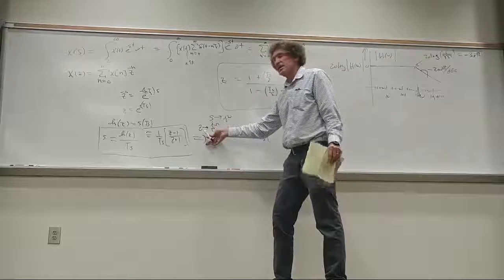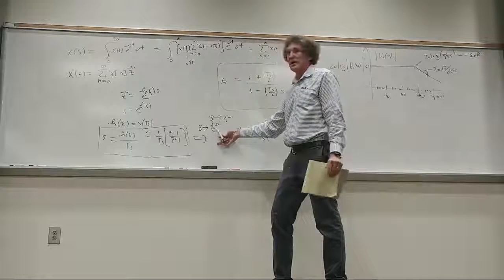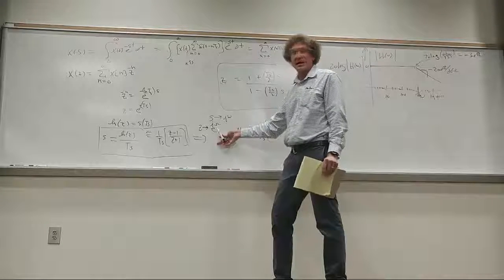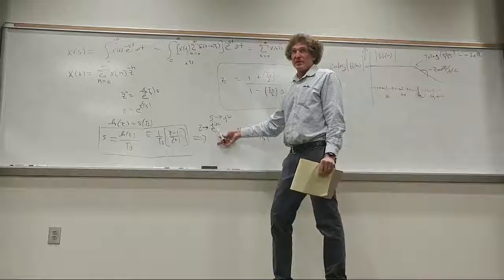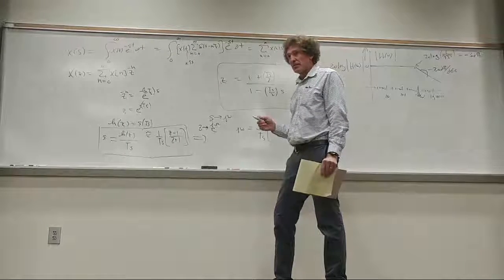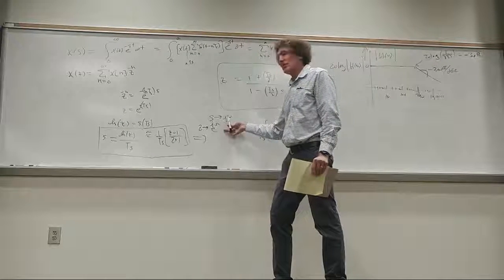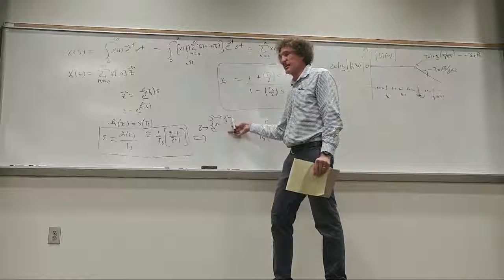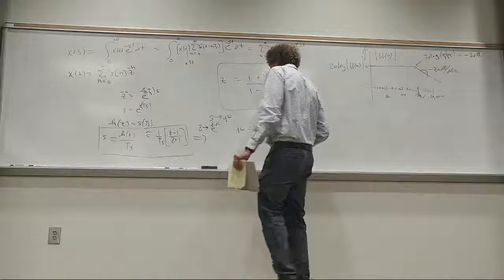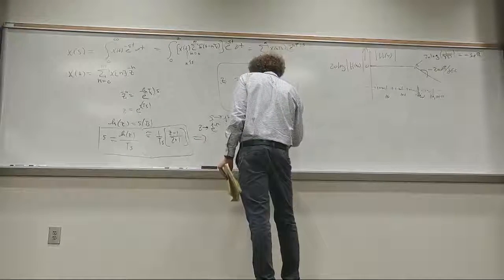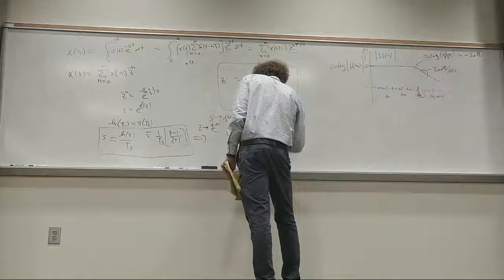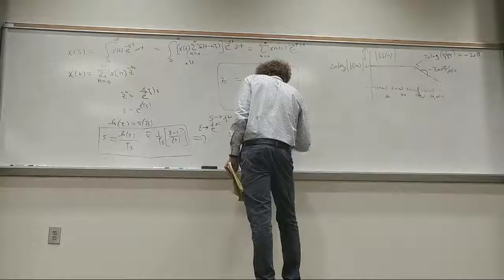We can also take Z, and if we let rho equal 1, now we're in the discrete time frequency domain. Now we have gotten rid of that, you might say, damping effect of the value of rho in front of e to the j omega, right? When it's 1. Now when you do this, we're relating continuous time frequency to discrete time frequency, capital omega. This is very important, right? So then if we do that, then this becomes e to the j omega minus 1 over e to the j omega plus 1.